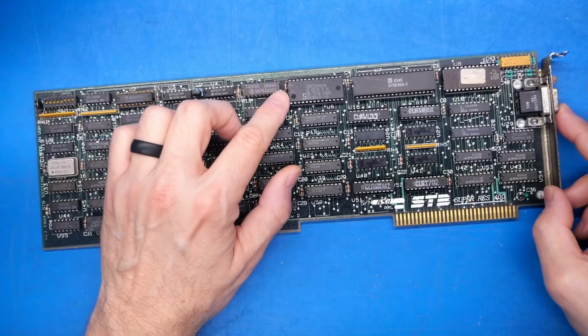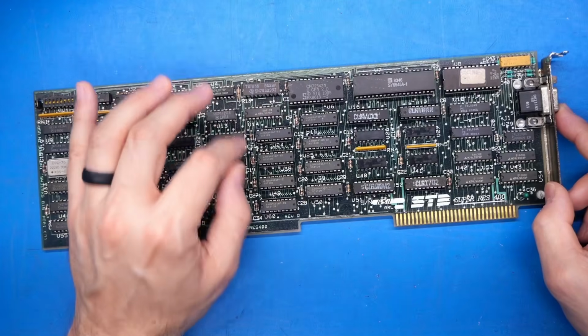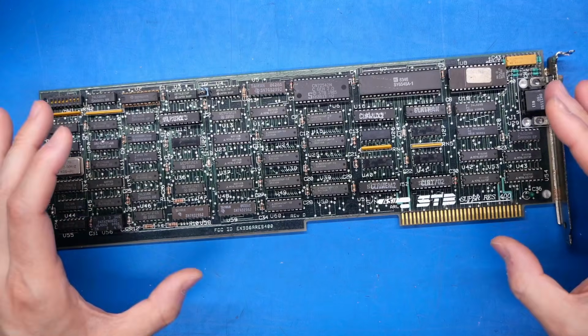In fact, the character ROM has a font in it. Instead of being 8 by 8 like a normal CGA card, it's 8 by 16 characters, which means that the text is a lot sharper and a lot closer actually to what you get on VGA. In fact, the IBM VGA standard uses a text mode resolution of 720 by 400 pixels at 70 Hz, while this card being 640 by 400 at 60 Hz means that VGA's font size, due to having 720 pixels across, is actually 9 by 16. But it really means when you look at the text mode output of this, it looks very similar to the clarity of VGA text, which is very different than the clarity of CGA text, which is very blocky in comparison.